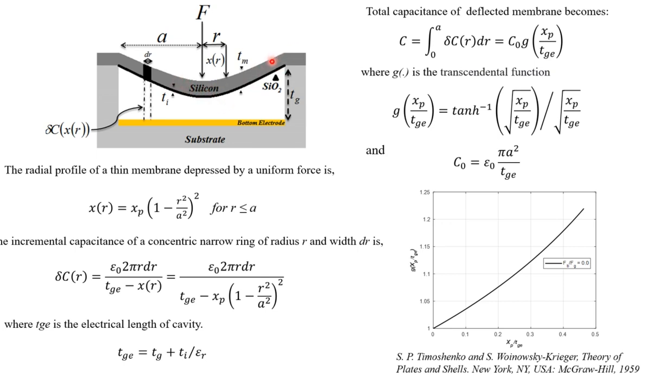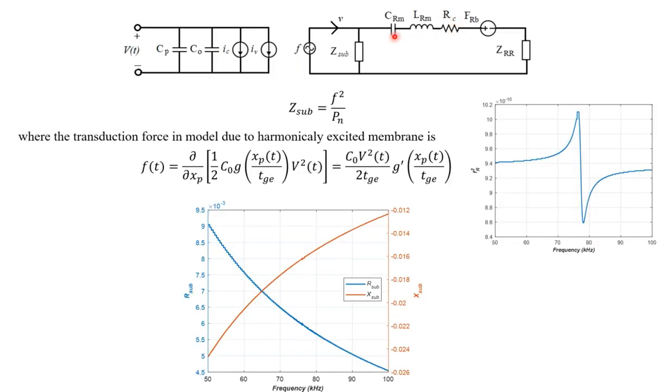So the displacement of the spring is in proportion to the force, as long as the geometric linearity conditions are maintained. But it's difficult to move the glass, so the compliance is very low as compared to what you have with the silicon front plate. So it's going to be a smaller capacitance, and that capacitance shows up over here for the glass.